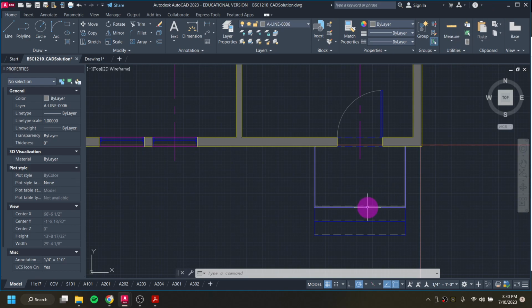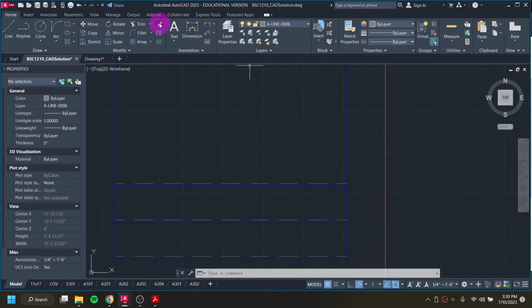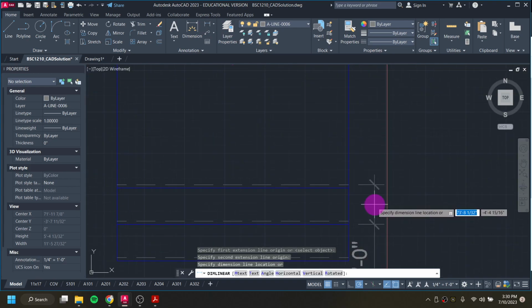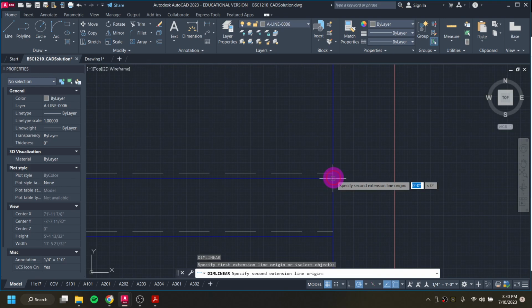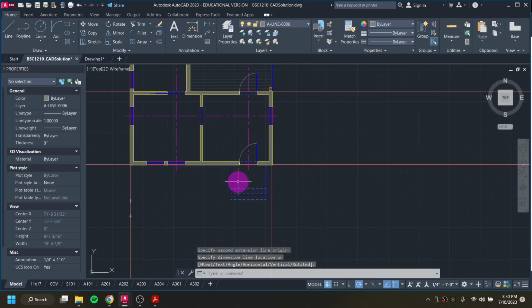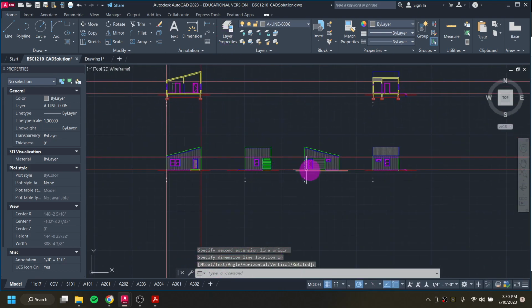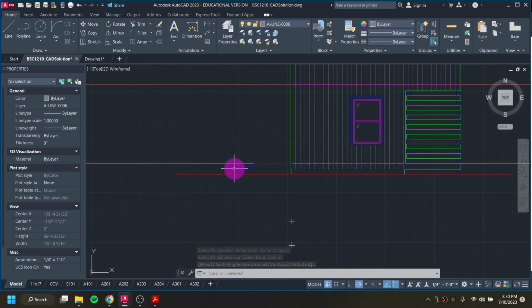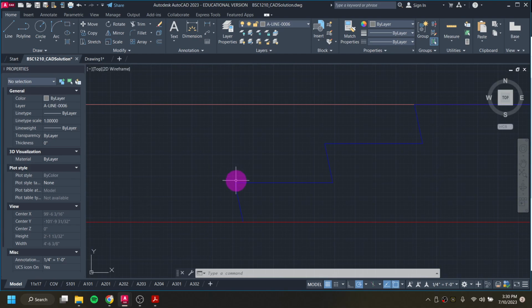So when we're looking at it, the 1 foot would be if we're measuring from here to here. That is 1 foot. However, these blue boxes, if I measure from blue to blue, are 11 inches. And that's because, as I described in the first video, when we have cast in place, solid concrete steps, they have this little bit of toe to it. And so the toe height is just referring to that slant.